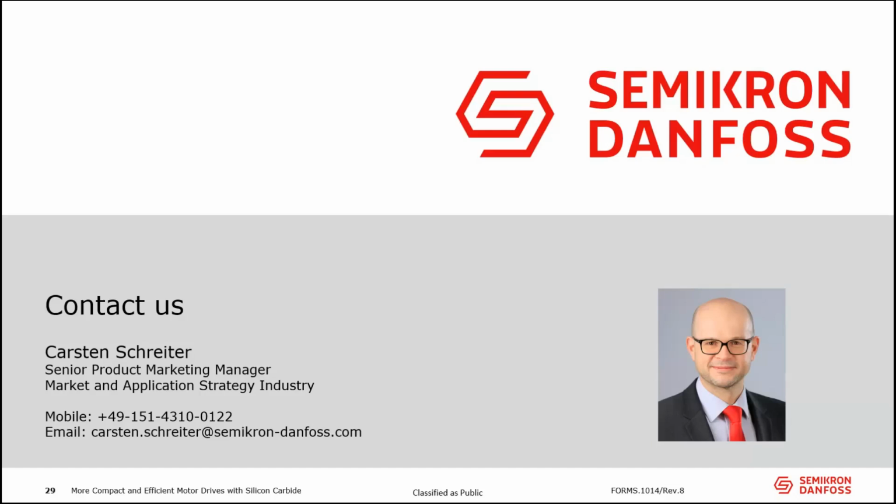I have another question about the freewheel diodes, asking if they're also made of silicon carbide, but I recall that you were saying that there were no freewheeling diodes on some of these devices. Maybe you can speak more about freewheeling diodes and silicon carbide. Yes, exactly. In the silicon carbide MOSFETs, we don't have an external freewheeling diode. The MOSFET always by its structure has an embedded body diode, and that body diode we use as the freewheeling path. So we don't use external diodes as we know them from the IGBT world. They're just not necessary here.